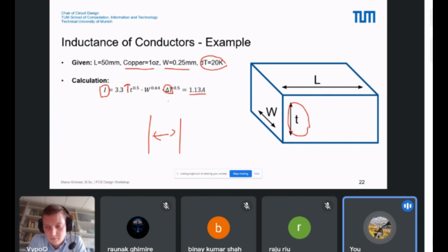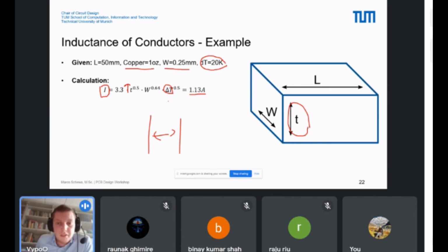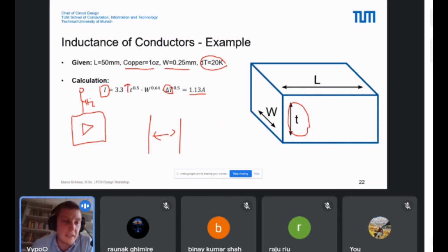And do we have to look at the data sheets about the ICs? Yes, it can be very helpful to do it, because a lot of data sheets also give hints about trace design or ground design or supply design. They always say, okay, if you have an amplifier IC, what is the size of the capacitor for the supply? It's also given in the data sheets. And also whether you only need an SMD or also an electrolytic capacitor and so on.